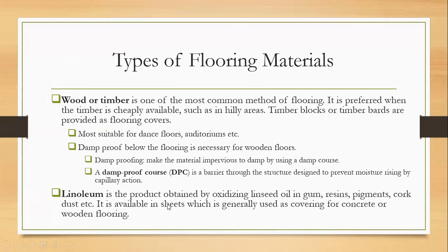But where you use wooden floor coverings, you need to be concerned about moisture. So you need to treat the wooden material with a course of damp proofing. That's a treatment that will be used to seal off the material from moisture penetrating the material, which would encourage the buildup of mold, etc.